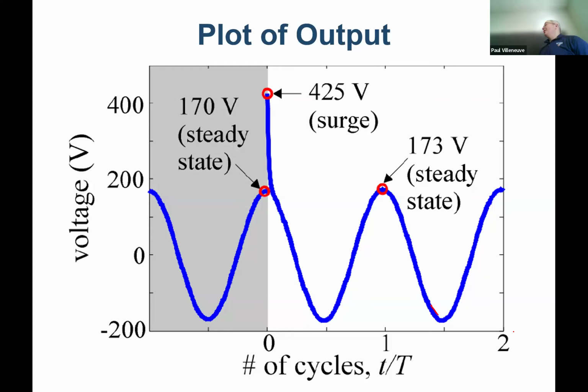And the only thing they would typically do is have a surge arrestor on the line, and mostly that's for lightning protection. So if you take the nominal voltage and multiply it by 120%, that's typically how high it would get before it starts to conduct. At your house, then, 120% of the nominal voltage might be too much to protect some of the sensitive semiconductors that you have. So those might be a different scenario, but you don't see a lot of stuff other than people trying to worry about switching transients.